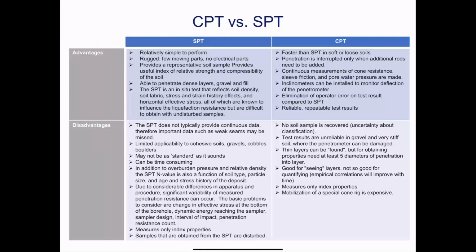So to summarize everything we talked about for this module, this slide is quite important. There are severe limitations with both of these methods because they're highly empirical, but they have their own charms or advantages. SPT is very straightforward. If you have an automatic hammer, it's even more straightforward, but if you have one of those pulley devices, it's probably more labor intensive. Even if it's labor intensive, the concept is quite simple. You just count how many blows and you measure the penetration of your rod. And the technicians can do that quite well.